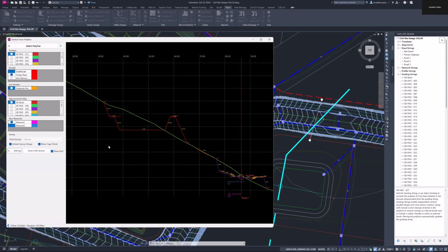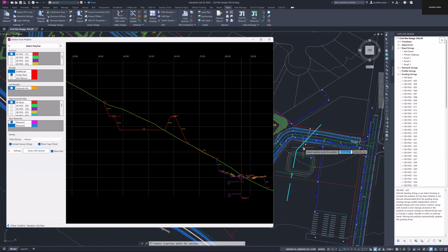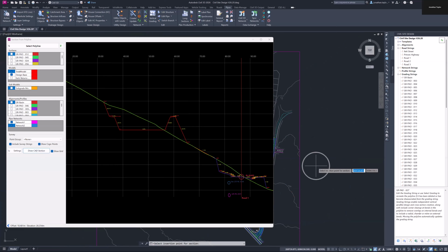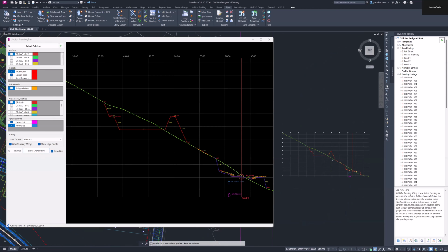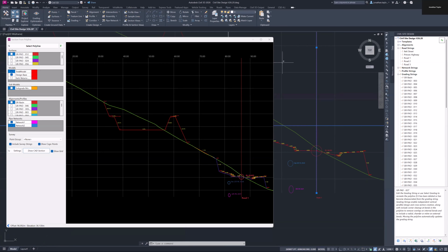The last part of this is to show you what you can deliver from this, which is a very basic but actually kind of handy CAD section. So if we click Draw CAD section, just jump ourselves into the drawing, move over, left click. This is a static one-off drawing of that section for you, which, to testify how static it is, is all on layer 0.